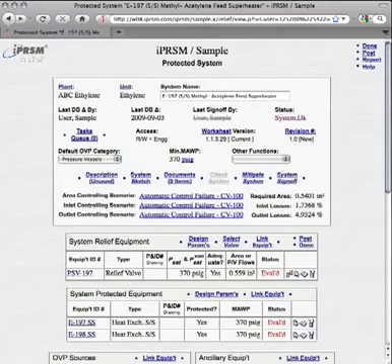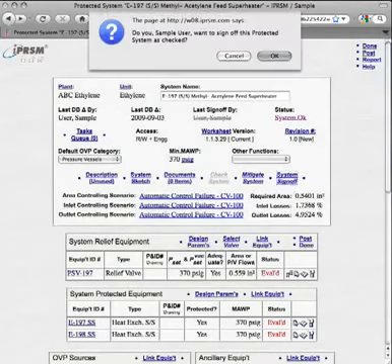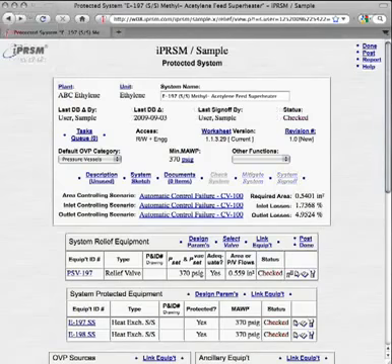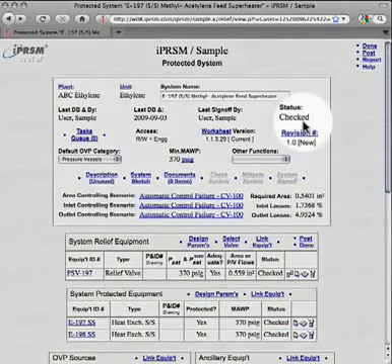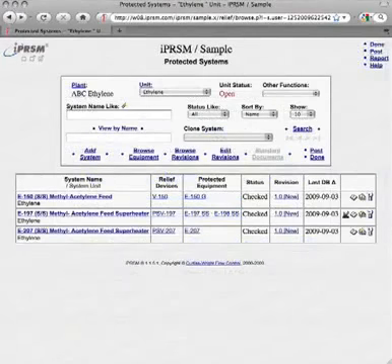We can see that the system checks out because the system status goes to System OK. Then we can sign off the system, and note that the system status goes to Checked. The techniques already shown in this video can be used to enter all the equipment, piping, fittings, systems, streams, flashes, scenarios, and piping losses involved in our unit.